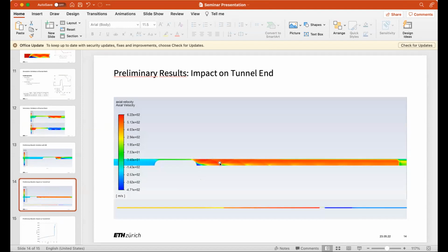There is some research being done on breaking down the shock wave at the trailing edge of the pod, which again would help drag. But what I've seen as more popular is the research being done in innovative shapes of the pod, because what we're seeing here with that expansion wave at the end of the pod is, well, our pod is just two hemispheres connected with a cylinder, and the ideal pod shape would more likely be something that looks a bit like the inside of a rocket engine. So there's been some research done into finding the optimal pod shape as well, and that might be a bit more significant, I think.